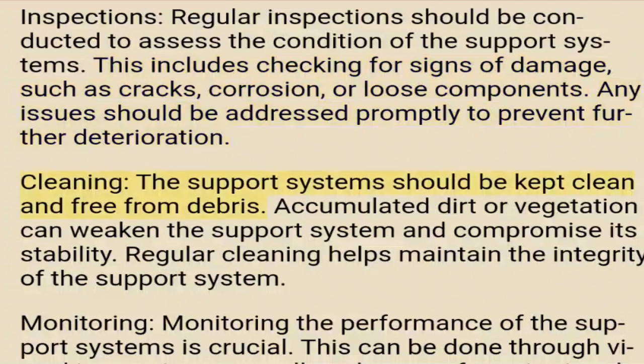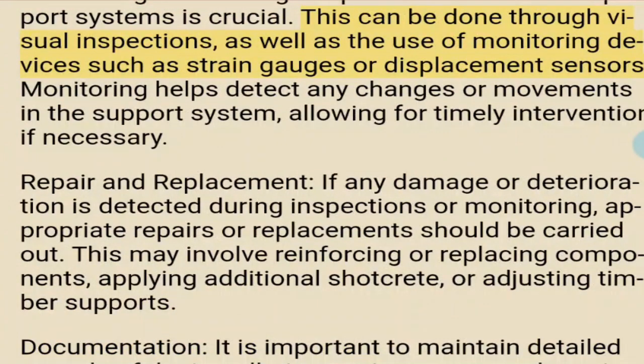Cleaning. The support systems should be kept clean and free from debris. Accumulated dirt or vegetation can weaken the support system and compromise its stability. Regular cleaning helps maintain the integrity of the support system. Monitoring. Monitoring the performance of the support systems is crucial. This can be done through visual inspections, as well as the use of monitoring devices such as strain gauges or displacement sensors. Monitoring helps detect any changes or movements in the support system, allowing for timely intervention if necessary.